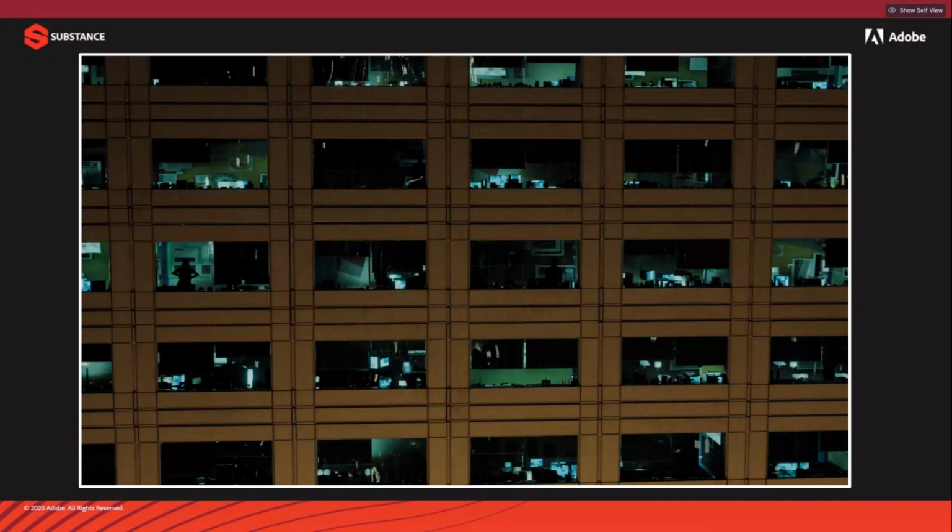I wanted to have a proper nighttime setup. So when you change the exposure, by just changing from a very high f-stop to a low f-stop, all the nighttime lighting would just appear. And change the time of day. So you change it from mid-afternoon to sort of 10 o'clock at night, and all of that detail would just appear without animating any lights or turning on any lights.